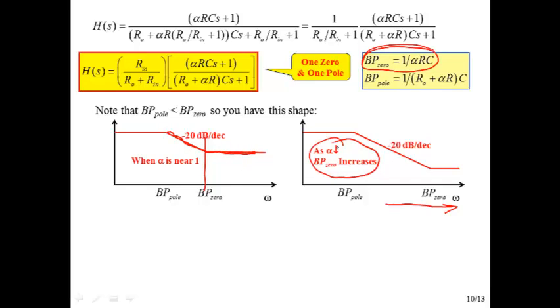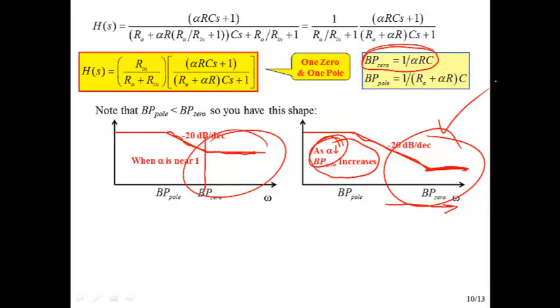As I decrease alpha, the zero's moved out, so it drops off a lot longer and then shelves at a lot lower range. So you can see that between the two of these, the one on the right is going to suppress high frequencies a lot more than the one on the left. And that's the action of this tone control.